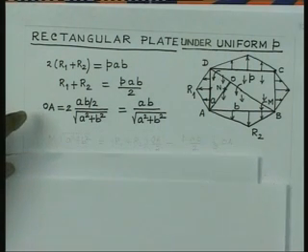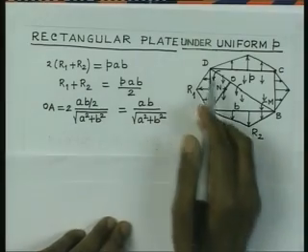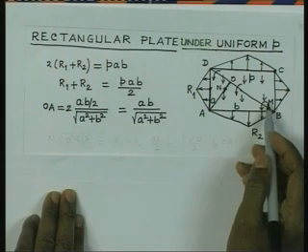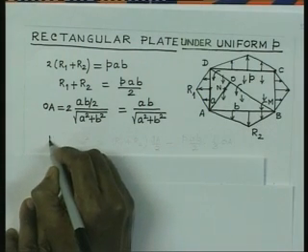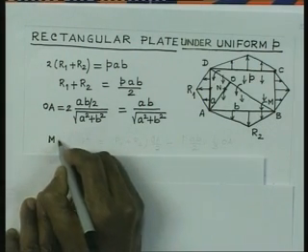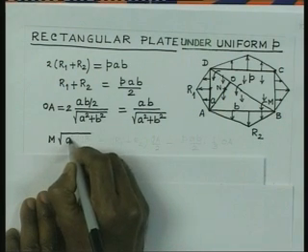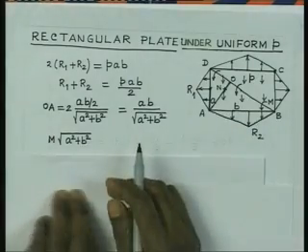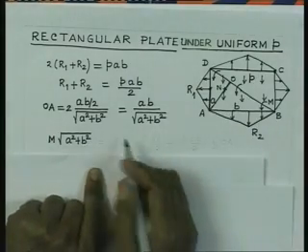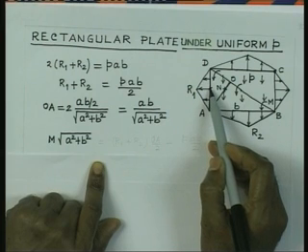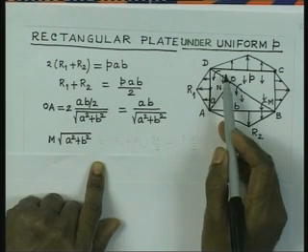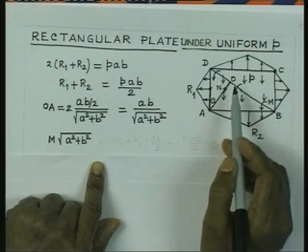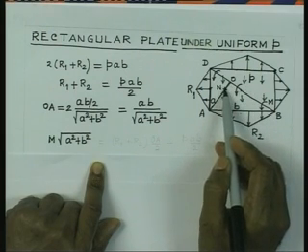Now, we go for considering the equilibrium about the line DB. So, if we now consider the equilibrium, we will have the anticlockwise moment, which is m, the intensity, multiplied by the total length, square root of A square plus B square, of the diagonal DB. So, that is the total moment in the anticlockwise direction. It is counterbalanced by the moment produced by R1 about this line DB, R2 about this line, and at the same time the distributed pressure acting downward through the point N.